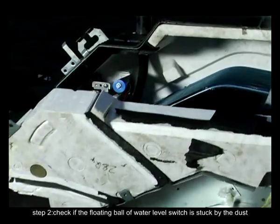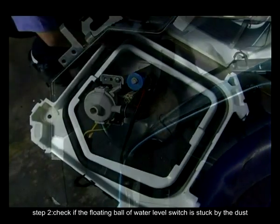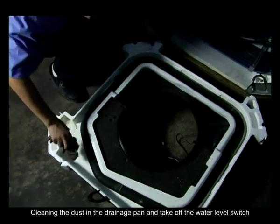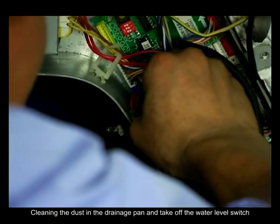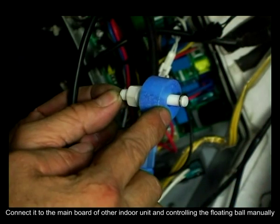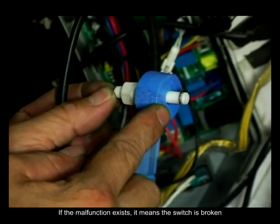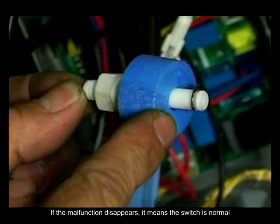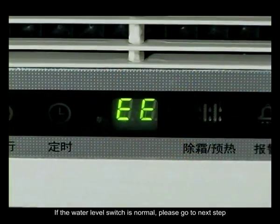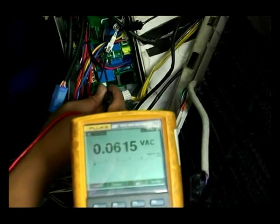Step 2. Check if the floating ball of water level switch is stuck by the dust. Clean the dust in the drainage pan and take off the water level switch. Connect it to the main board of other indoor unit and control the floating ball manually. If the malfunction exists, it means the switch is broken. If the malfunction disappears, it means the switch is normal. If the water level switch is normal, please go to next step.